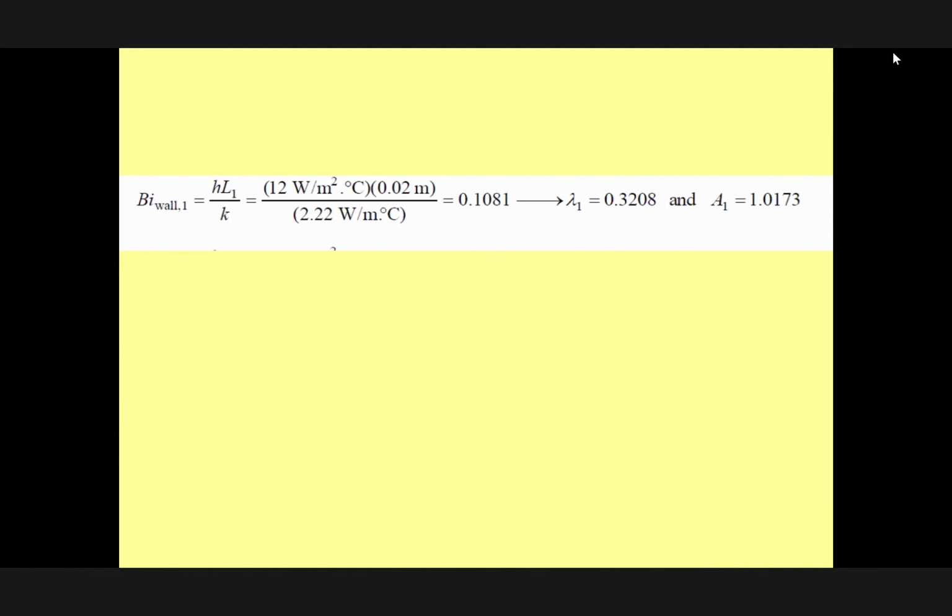Now, it either happens on the plate, anywhere, or at the edge. If you look at, let's say, the worst case scenario at the center, on the top surface at the center, you have conduction through the ice in this direction, and you have conduction coming here and conduction here.